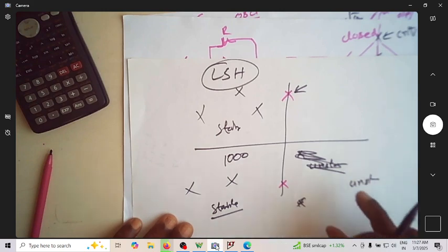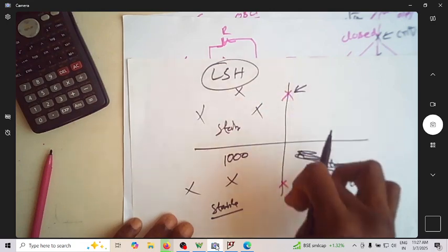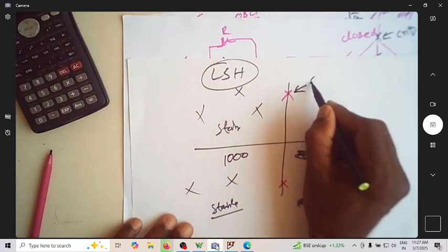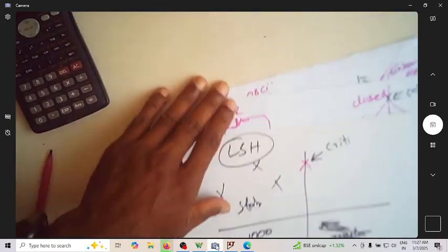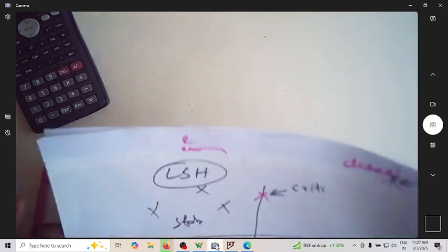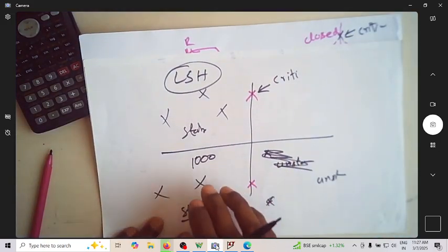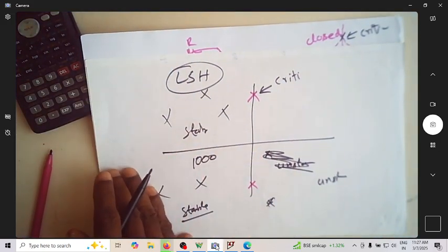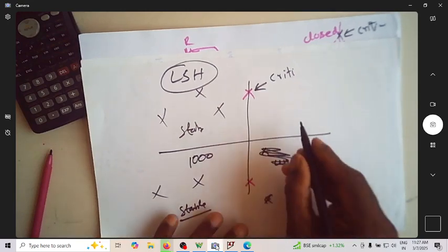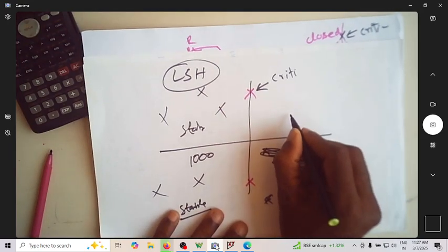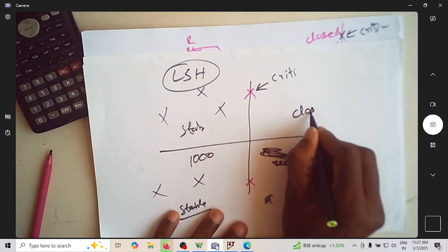If a minimum of two poles come on the imaginary axis, the system is critically stable. Because we are so worried about whether it is on the left hand side, right hand side, or on the imaginary axis, we give so much importance to closed loop pole position.